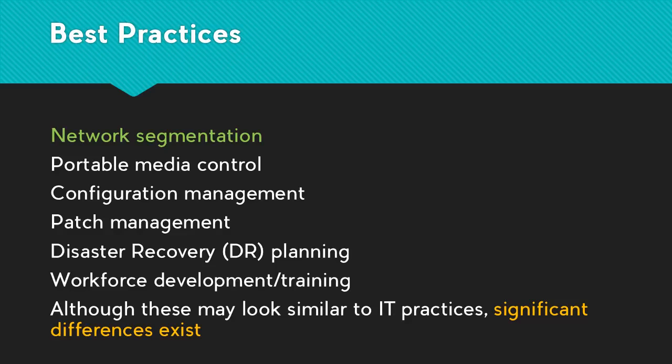So what happens when you patch against the latest IE use after free vulnerability? Or if you patch away how Windows SMB communicates, SMB signing, things like that, you break it. You have nobody to support you now. And even in software that is currently supported, that you buy from Siemens and Emerson and GE, they're going to tell you, we're only certifying that this software will work at this OS level with this patch level. If you deviate from that, we're not going to support you, or we're going to make you roll back to the version that is supported. So patch management is a crucial issue both for the IT side and the OT side as well.